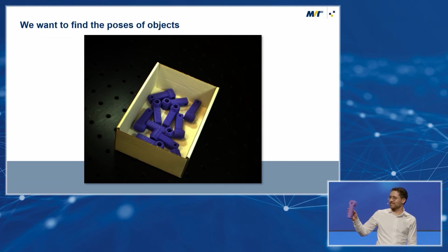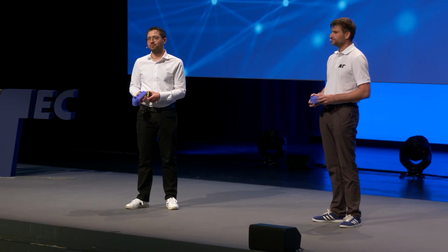You can see, for example, that the backside, which was at the bottom of the 3D printer, has a different texture and different surface characteristic compared to the remaining parts. Some of the edges are rounded, which means that if we see these edges in an image and the light reflects in a particular way, we will not see them at their correct location. Another thing is, it's not really precisely manufactured. We have a cut file for this, but the 3D printing has some thermal properties, so I think this is off by a few millimeters. So manufacturing can be somewhat imprecise, the edges can be imprecise, and there are other parts you can think of, like reflective metal, for example. All of these are very difficult to detect in images.